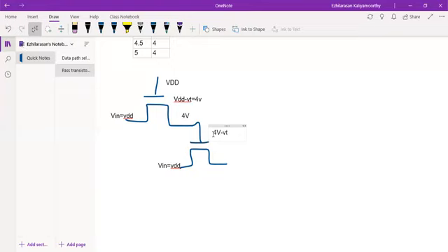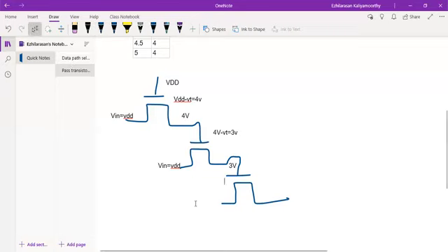VT is equal to how much? It is 3 volt, the maximum it can deliver here. But my input is how much? 5. So here how much volt will I get? It is 3 volt only I will get. Even so, if you are using one more pass transistor, if this is driving this, then when I apply the input here as Vin is equal to VDD.